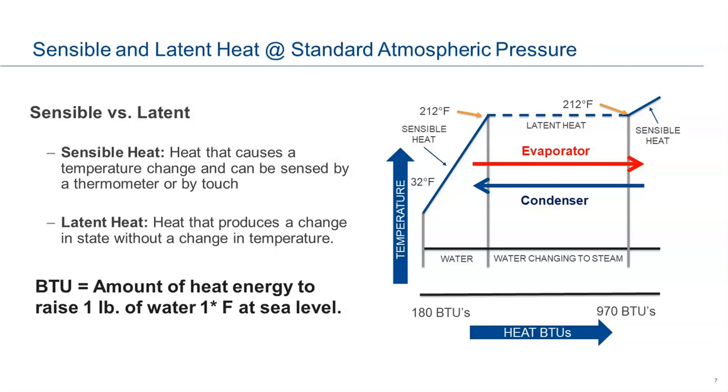So all the way from 212 to 212 at the end, it's not until that very last drop of liquid goes out of the pan that it will change the temperature to 213. And that 1 degree over 212, when it turns to a vapor, is sensible heat, but it's also superheat. In our industry, that is the evaporator. That's also the condenser going back from the vapor to a liquid, okay? And that's how that works.